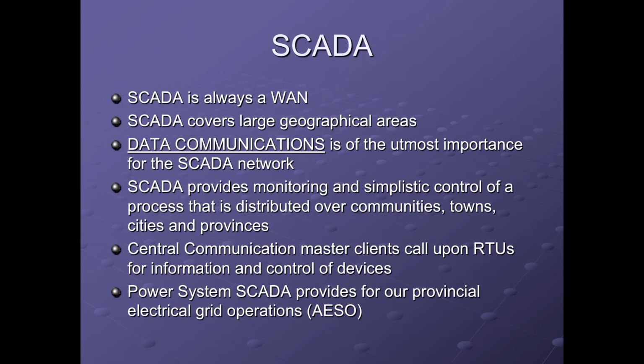Another acronym is AESO, Alberta Electric System Operator, and they monitor, supervise and control all of the generation, distribution, and transmission of electricity in our province. If you were to connect to our grid, you would be required to provide certain SCADA variable data to AESO so they could look at what you're doing in terms of generation and what's online and what's offline, and they could make choices about load shedding and all that kind of stuff.